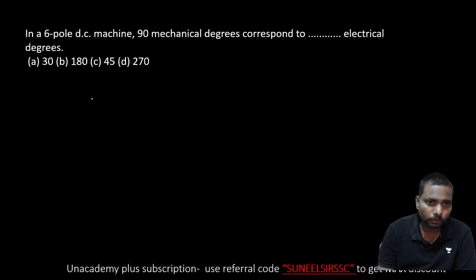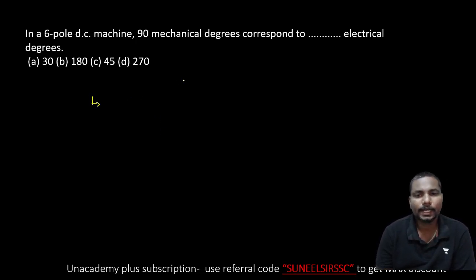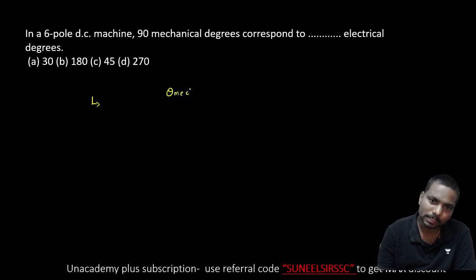In a 6-pole DC machine, 90 degrees mechanical corresponds to dash electrical degrees. We know very well theta mechanical is fixed. Theta mechanical is always fixed. Mechanical degrees is 360 degrees, but theta electrical depends upon the number of poles.